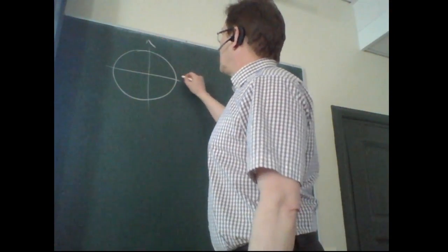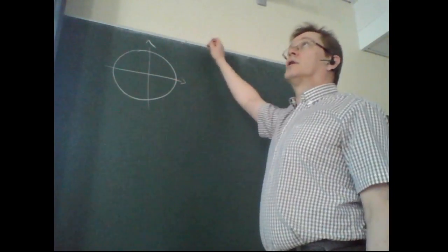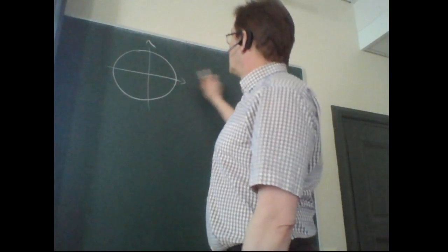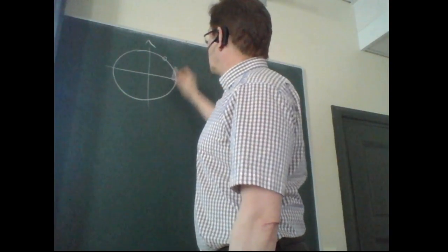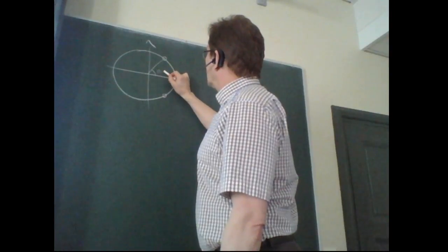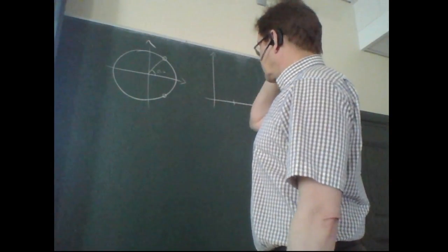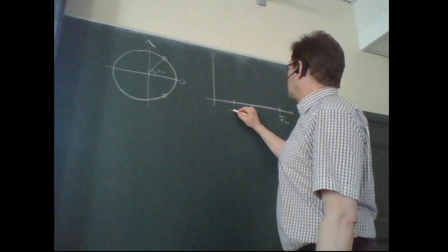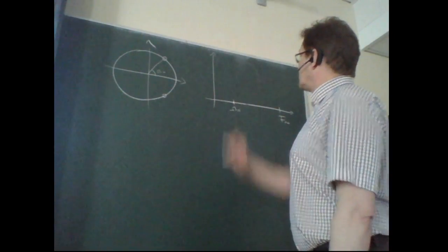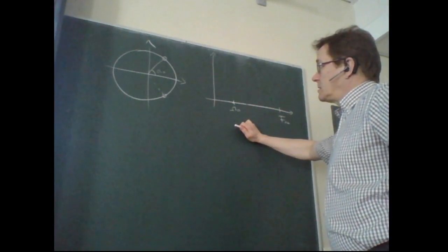So basically, the first IIR filter, the easiest one to design, or actually the only IIR filter you can design in pen and paper, is practically the notch type of band stop filter, where you set a pair of zeros on the unit circle, meaning that at this angle omega n we have total attenuation of the signal. Nothing comes out on that frequency.